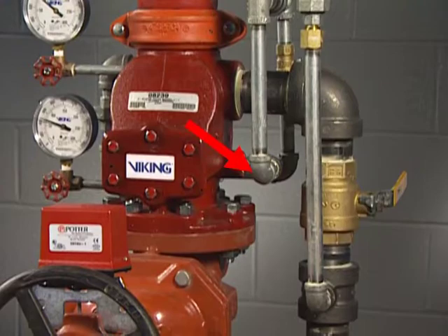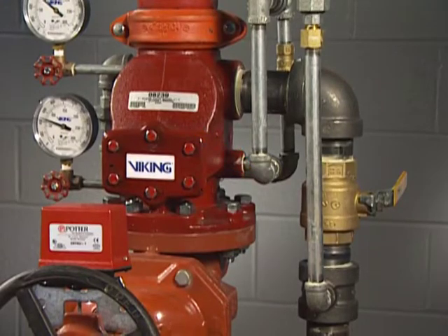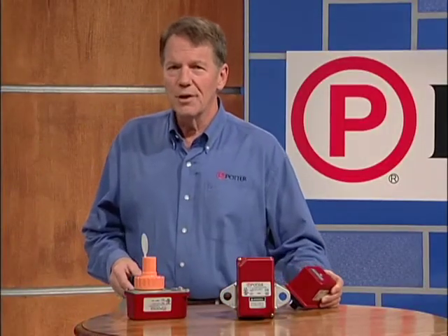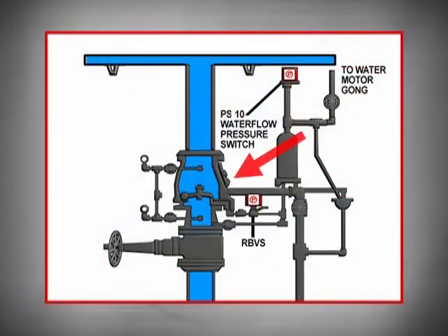Some of this water is diverted through piping called trim to activate the pressure-type water flow switch or ring a mechanical bell called a water motor gong. Under normal conditions, the alarm valve traps pressurized water above the clapper and prevents reverse flow from the sprinkler piping.